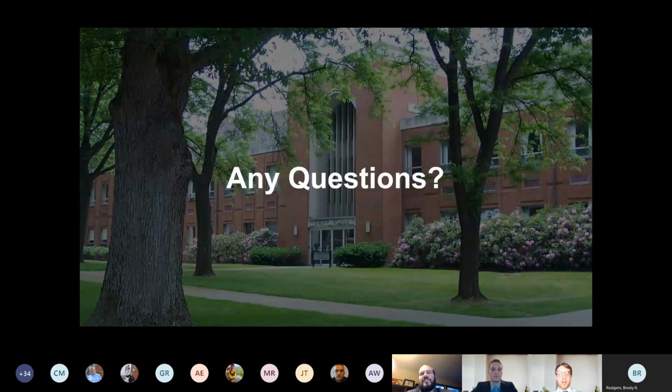So I'll answer that if I can. Actually, believe it or not, the machine shop and the bathrooms are not allowed to have returns in them by ASHRAE standards. So we actually have them exhausted to the outside, or in the case of the machine shop, we would have that air run through a filter if it needed it. But in this case, it can be exhausted directly to outside. That air cannot be returned through the plenum.